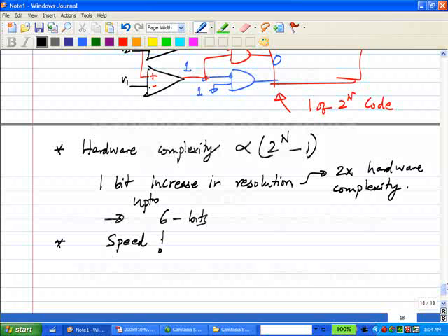In other words, you can't say, you give me the input, I'll tell you the code tomorrow. Presumably, if you can take a lot of time over something, you can do it efficiently. But if you want the answer now, you have to pay a price in terms of complexity and power. Basically, more parallel blocks means more area and more power, because you have to pay all their salaries. And you're paying bias current every time you run a block. So this is only used in applications where speed is absolutely critical. In what applications do you think speed might be a critical issue?